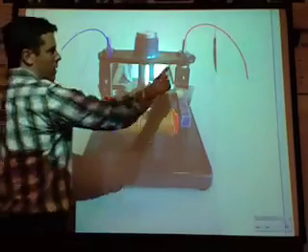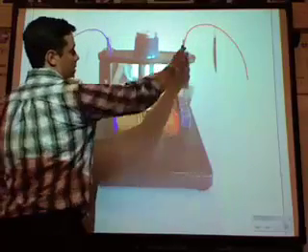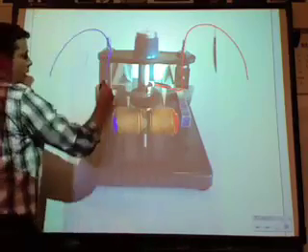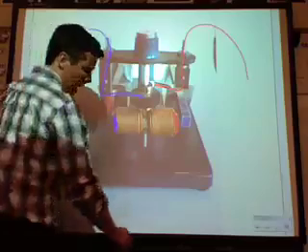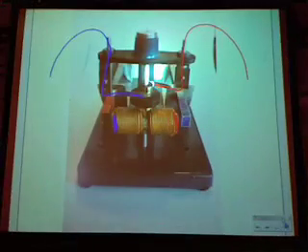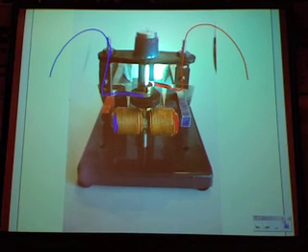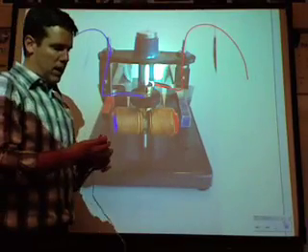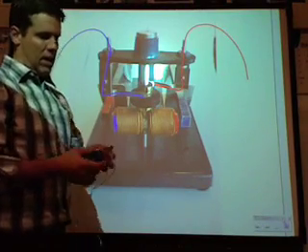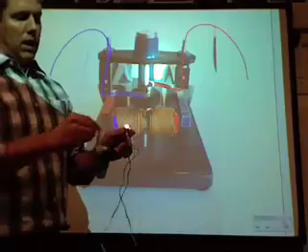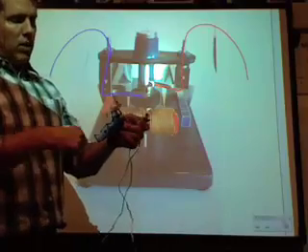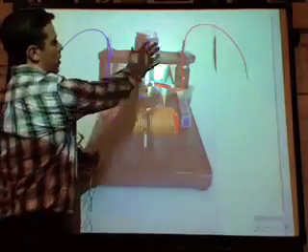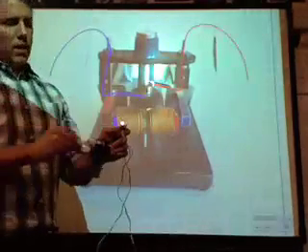If you trace the path of this wire, you can see that it comes down and connects through this little metal flap called the brush, just like the brushes we had in our generator. I showed you previously that a generator has to have a way to keep the wires from getting tangled. Okay? Remember, we crank the handle, we get electricity, and there has to be a way to do that without these wires getting tangled up there. If this were permanently attached to our connections, the wires would get tangled.